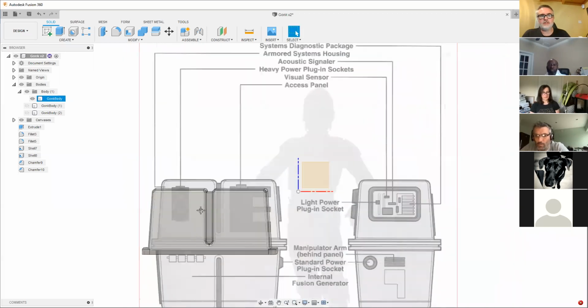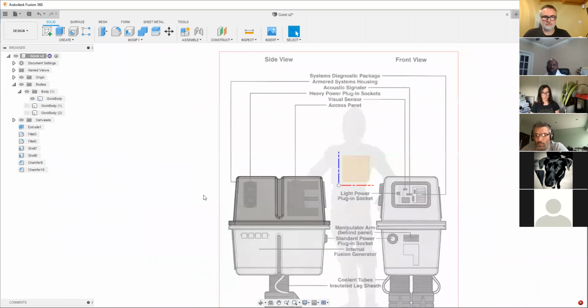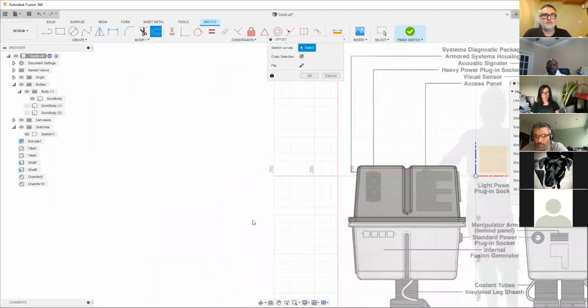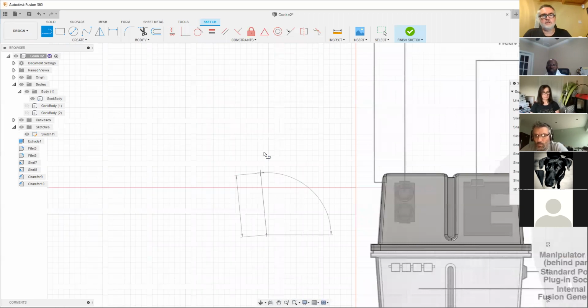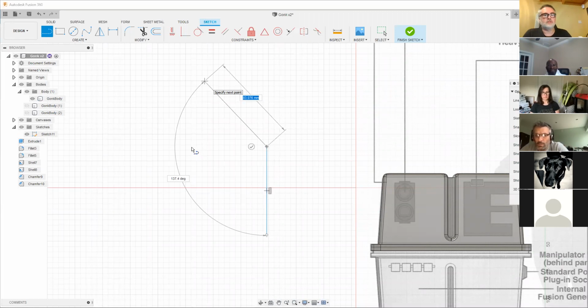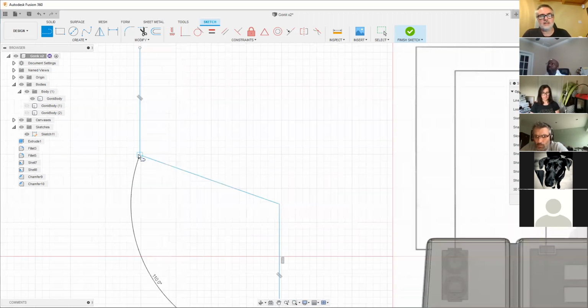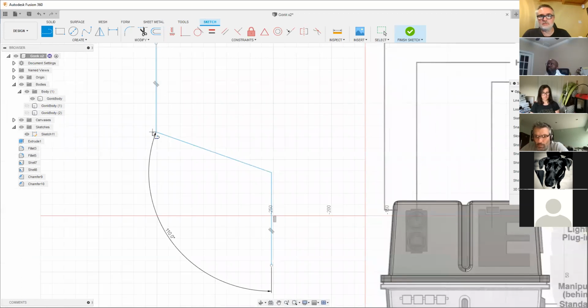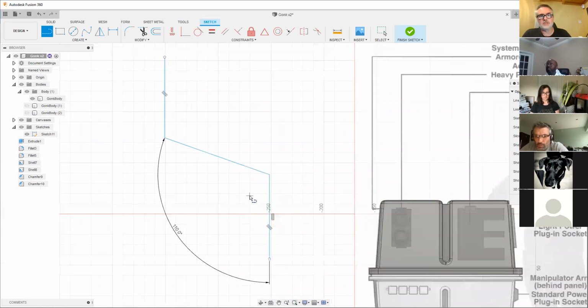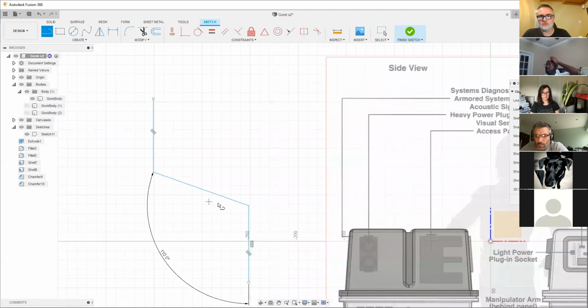So if you can keep thinking about that as you go through, from experience, a 45-degree angle on the inside will give you a really clean print, without a doubt. But you can actually get down to about a 20-degree angle. I can print that as an overhang. Now that'll give you a messy-ish print, but it will print reliably as an overhang. So as something that's inside the model that you wouldn't see, that would work fine.